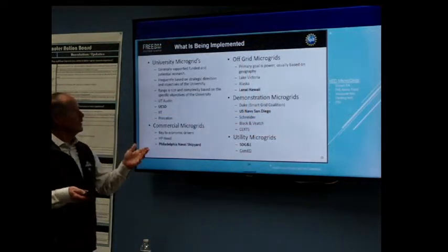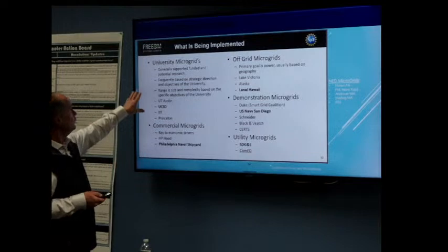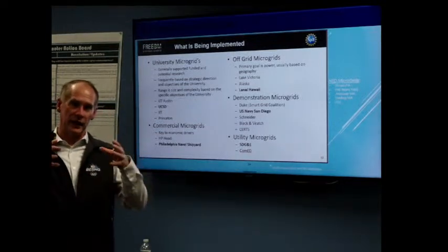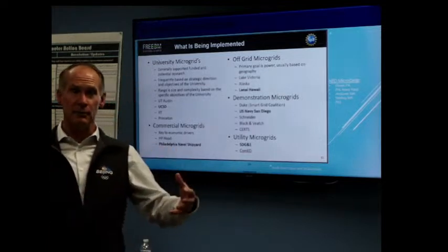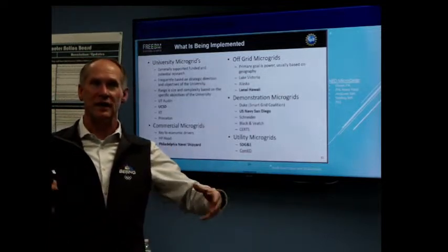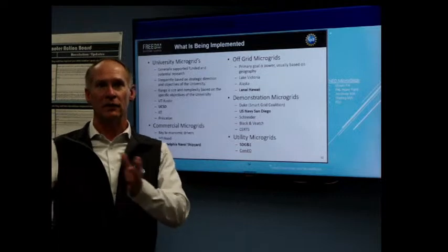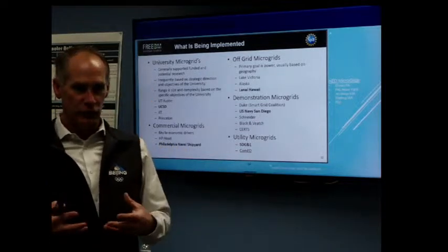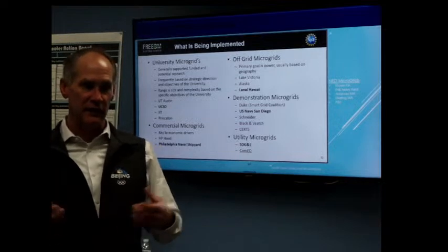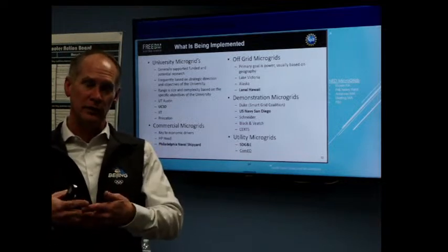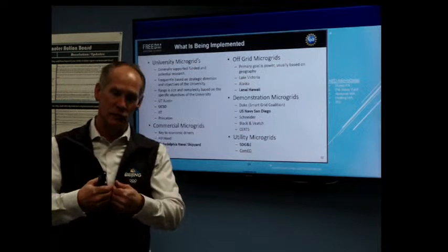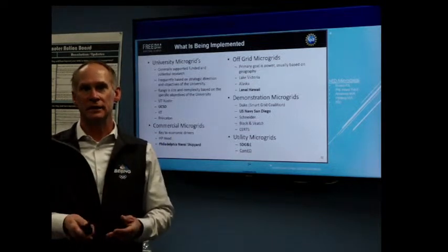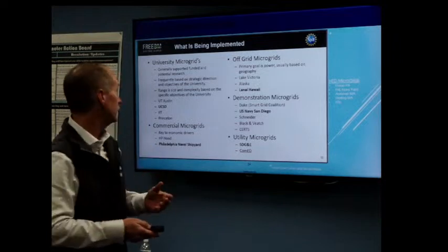So what's being done about it? There's been a push to do what's called microgrids. Microgrids are a way for a single building or a campus of buildings to successfully operate without a utility source for a long period of time. A microgrid is really taking advantage of any means of energy input and any means to utilize the energy while you're isolated and islanded from the utility structure.